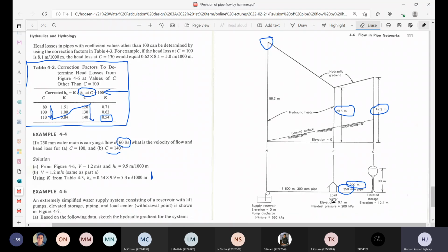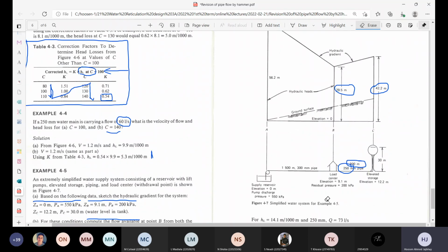We know how much we need there, and then we see, okay, we're starting the supply from a particular point, and we install a particular pipe size, and then we see whether that amount of water actually arrives at that point, and what is the head loss in that pipeline? If the head loss is too high, then we would increase the pipe diameter. But you'll see that procedure in next week's lectures.